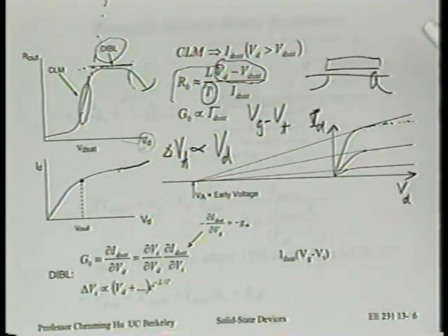Yes, question. From that expression, we said that for a large R naught, we need a small L prime, and therefore we need a very small oxide thickness. Yes. But the oxide thickness dependence of ID sat is much stronger. So if we take the Tox dependence from ID sat into consideration, we would get the opposite dependence. Okay, let's do one thing at a time.